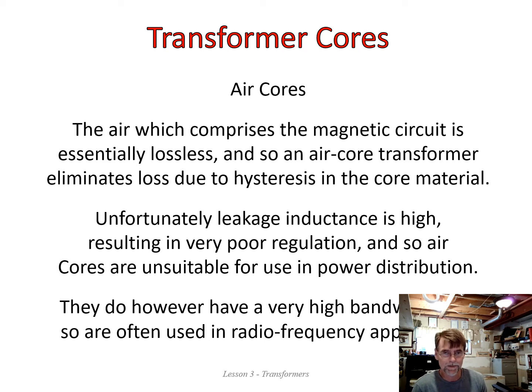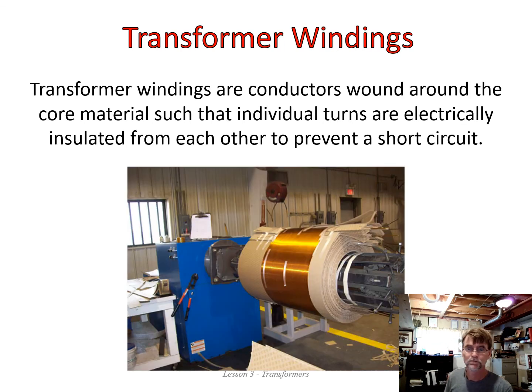So the final statement there, though, says very high bandwidth. So good for radio frequency applications. So again, we're talking about as you increase the frequency, the changing of direction, so the flip-flopping of the magnetic field and the changing of the direction of the current. So back to that word hysteresis, not a problem in an air core. So an air core is probably the way we want to go in extremely high frequency applications. For our typical power distribution at 60 hertz, air core is probably not the right choice, and it really never is. So that is the core material.